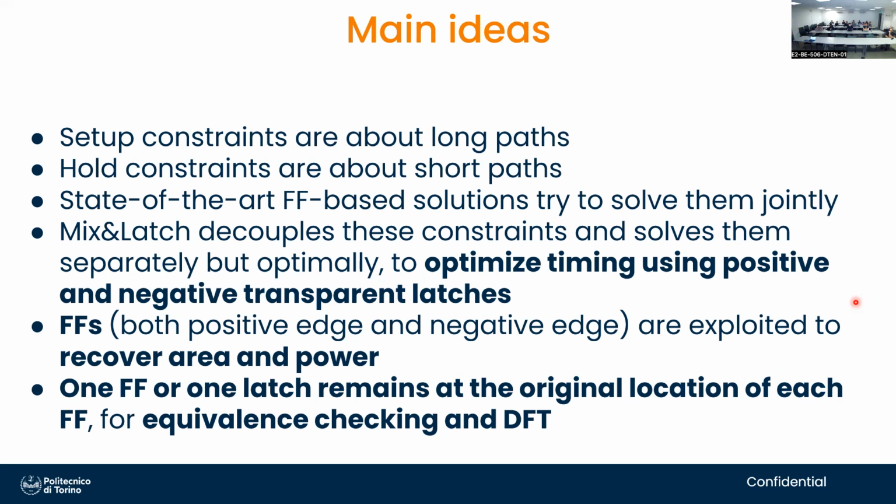Moreover, there is a second constraint that you don't have to go through too many open gates at the time in every clock period, since this is a synchronous system where everything is controlled by one general clock that tells every flip-flop, every latch in the system when they need to open and close. We want every runner to go through one memory element exactly through every phase. So if they have a short path to go, they shouldn't be able to go through one and go through the next and be captured by the second one.